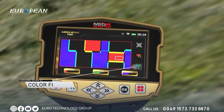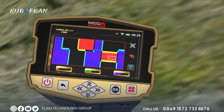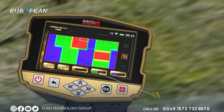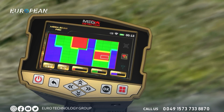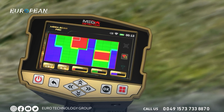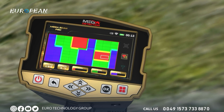Color filter. Use this option to hide or show the green color, representing normal ground. This is useful for showing areas of the scan that include metal targets or voids. Color ratios. The 3 color bars, red, green, blue, represent the percentages of each target type within the specified cell from the scan area. Average. This field represents an average value of all values in the detected points. Depth. When the selection is made on the cell, the depth value will appear in the lower information bar, and the user can see the depth in each cell with this option.